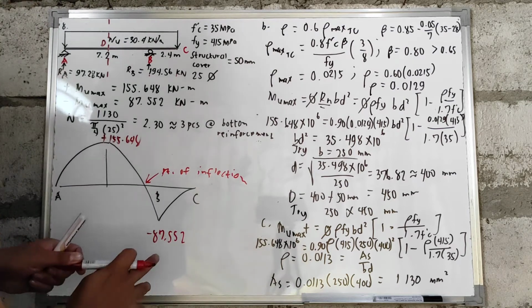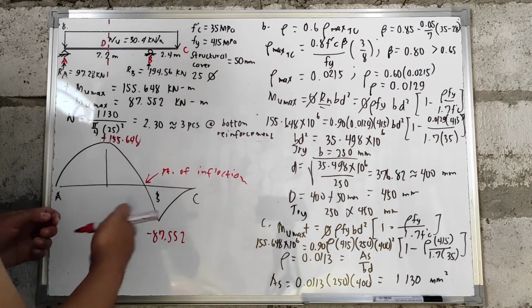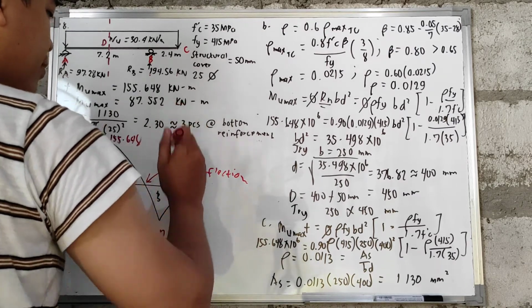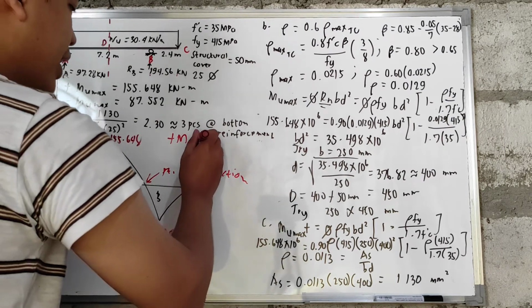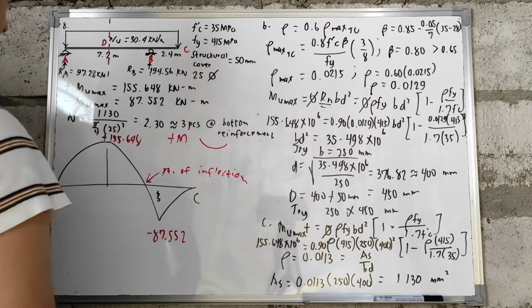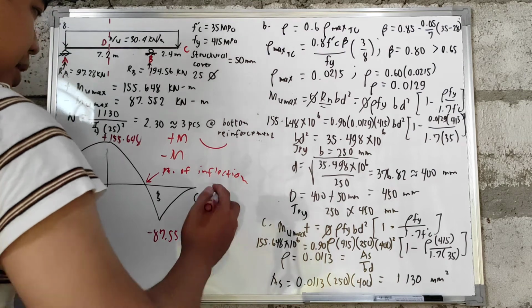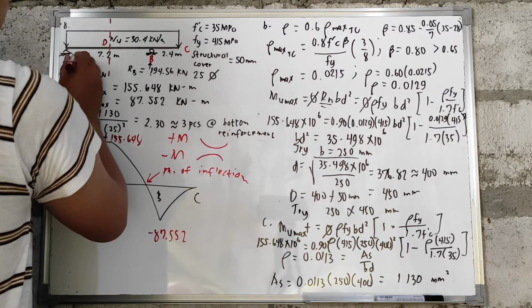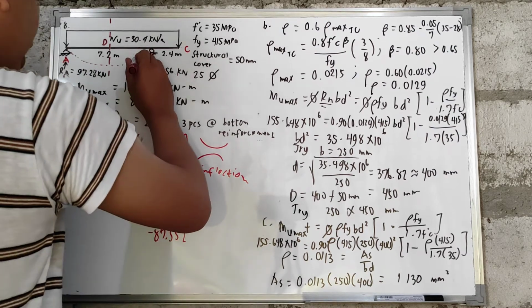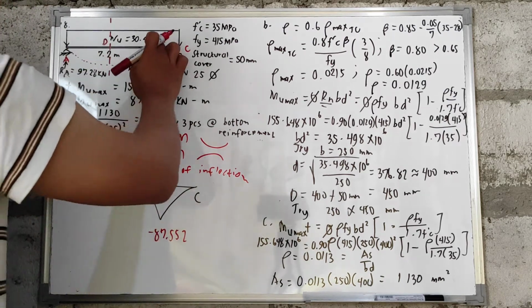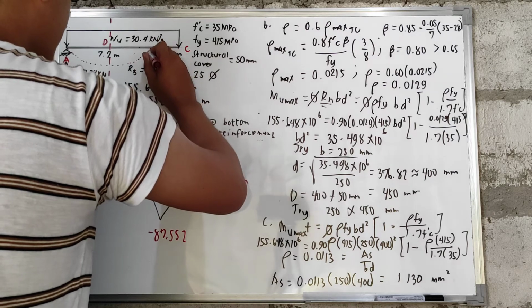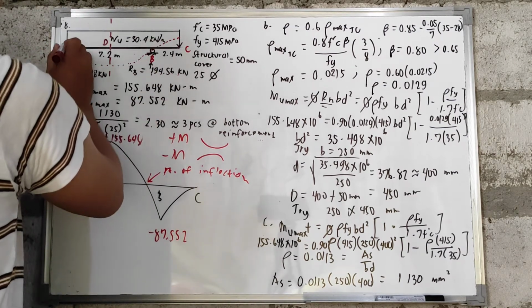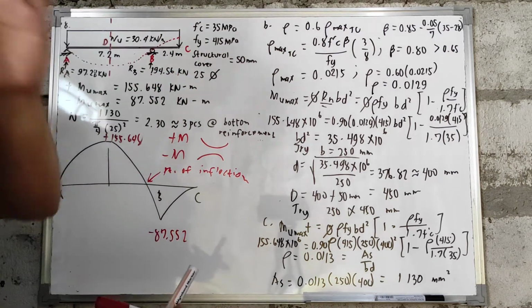At the point of inflection, our elastic curve changes. So let's say our point of inflection is here. At this point, since we have a positive moment, the response of the beam when deflecting is that it smiles. When it is a negative moment, the response of the beam in deflecting is a sad face, or concave downward. At the point of inflection it changes, from concave upward to concave downward. It passes through here, and this is now its deflection. The deflection goes to zero at our supports, so from concave downward it suddenly shifts to concave upward. This is how our beam will deflect.